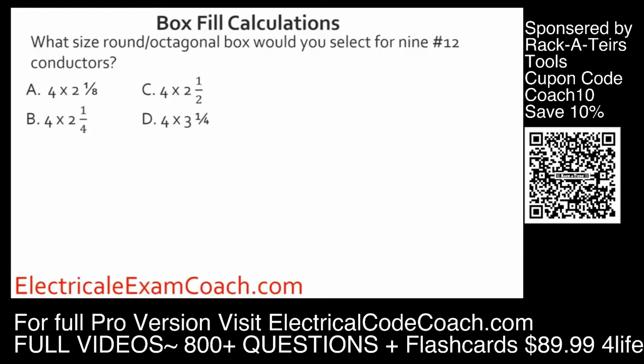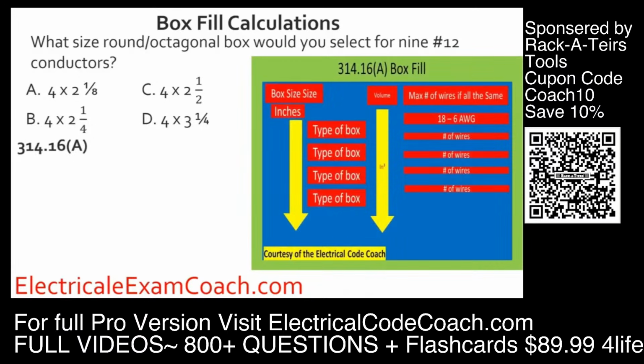What size round octagonal box would you select for 9 number 12 conductors? For this one, we're going to be using table 314.16(A). We're going to start here and find our gauge of wire. Then we're going to come down and find a box, making sure to cross over and double check that we don't cross over into a different style box. We want to stay in the round octagonal. We find our conductors, we find the one that fits it, we slide over and double check ourselves, and we're going to select A. Great job!